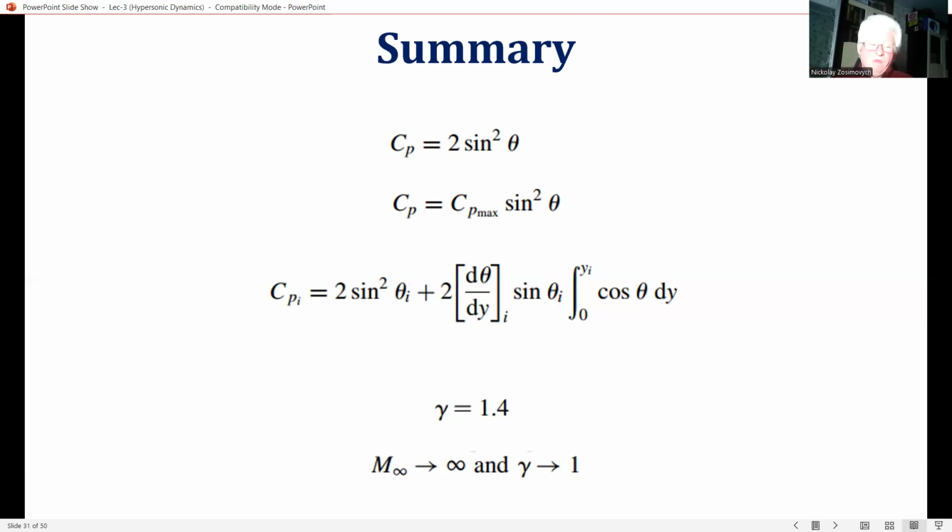Of course, for surfaces with large inclination angle, I mean greater than the maximum deflection angle for an oblique shock wave at the given Mach number, the Newtonian method is, in this case, appropriate. Within the confines of the Newtonian method itself, for blunt surfaces where theta is very large, modified Newtonian is best, whereas straight Newtonian usually yields better results for slender bodies.